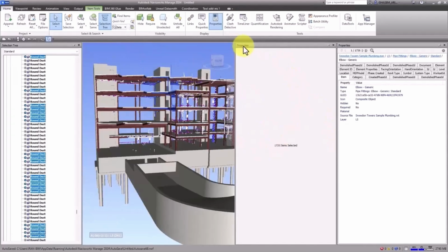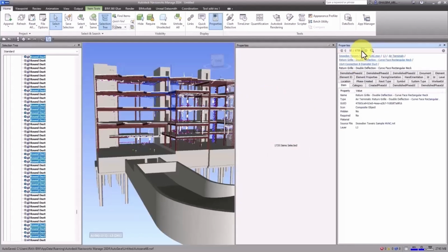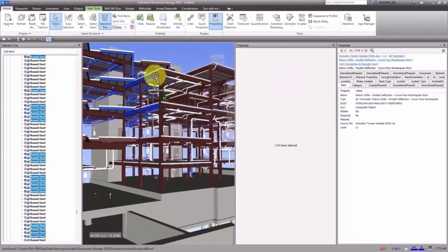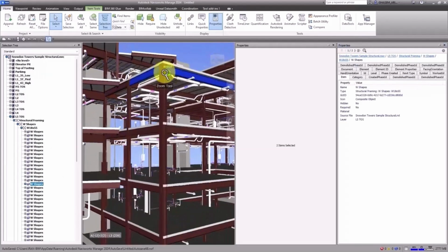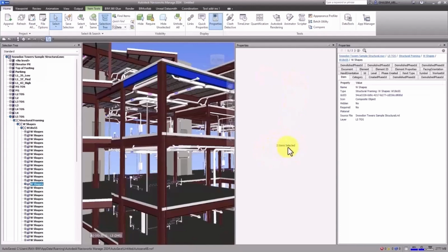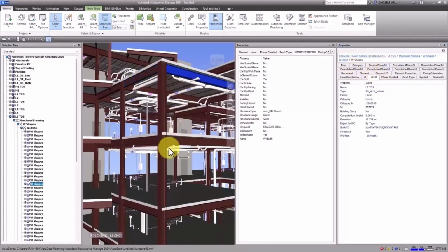As an instance, when I select some items, there is nothing in the properties window of Navisworks, just the number of selected items. But here I can see and check 1535 selected items. With next, I can check each one I want. Guys, we don't need to check this number of items at the same time, but sometimes you might have 2 or 3 items and you want to compare them. But it's not possible here. But here in the plugin, item 1, item 2, with this information, and I can compare the parameters.